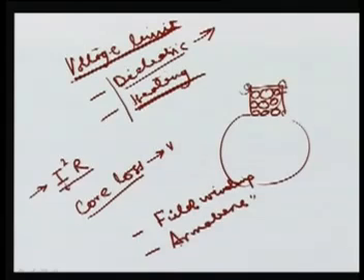Another is called the end zone, due to the corner and surface, and that is another heating limit. So with these heating limits, our generator should operate within those boundaries, and we should not go far beyond its allowable heating limit.